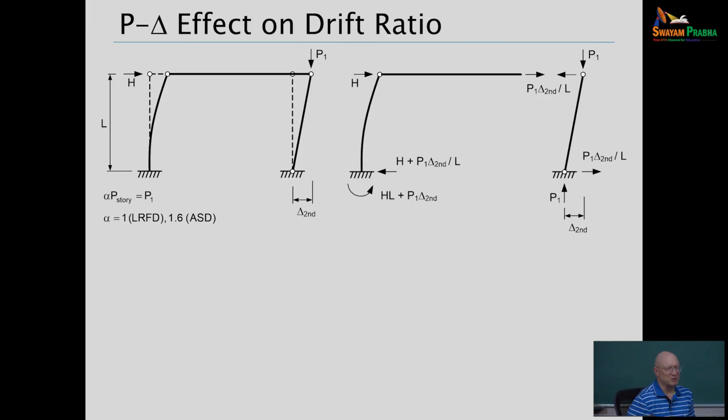One of the solutions, and the solution that failed, was kind of a clever solution. So we have LRFD load combinations that have a more scientific or probabilistic basis. Some of the ASD combinations were kind of more historical, so that's where things got all messed up. And the clever solution was: just take the LRFD load combinations, divide by 1.5, and adopt those as the ASD load combinations.